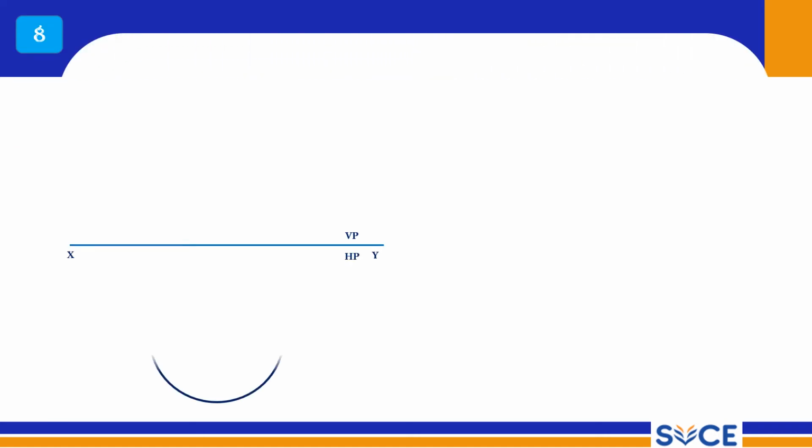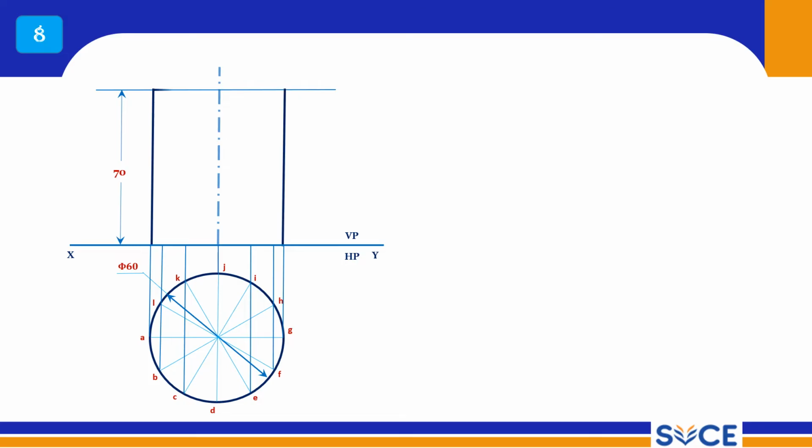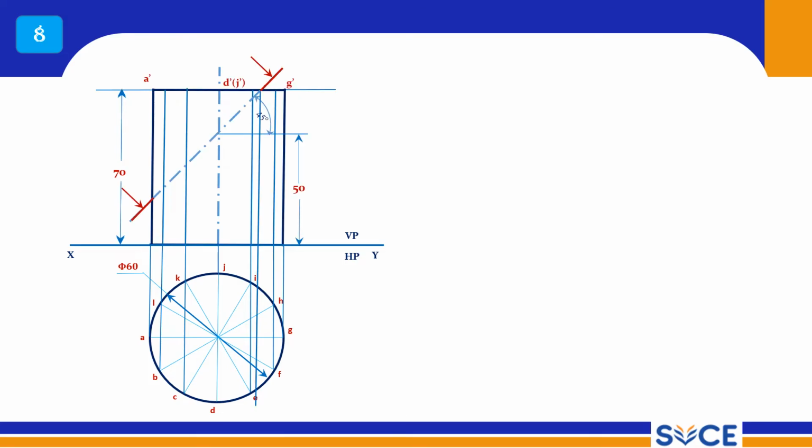To start this problem, draw the cylinder and divide it into 12 equal parts. Draw the front view of the cylinder and cut the cylinder at 45 degrees. Mark the cutting points. One is on the A generator, 2 is on the B generator, 3 is on the C generator. Similarly, mark the cutting points.